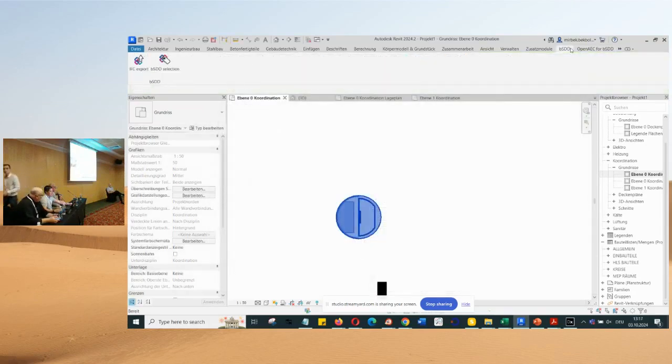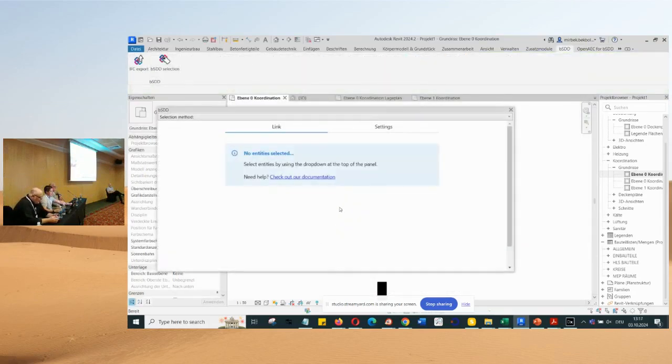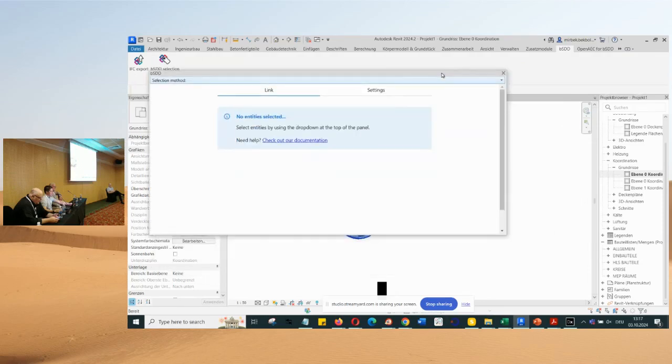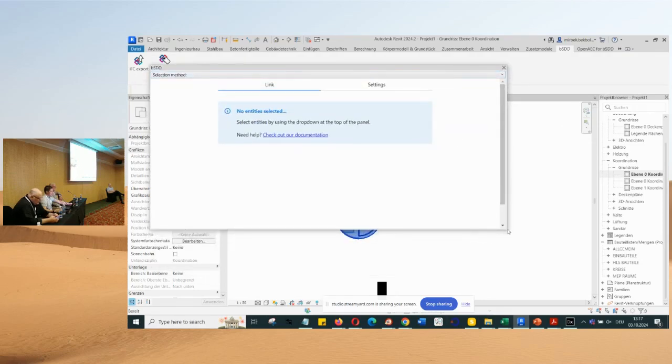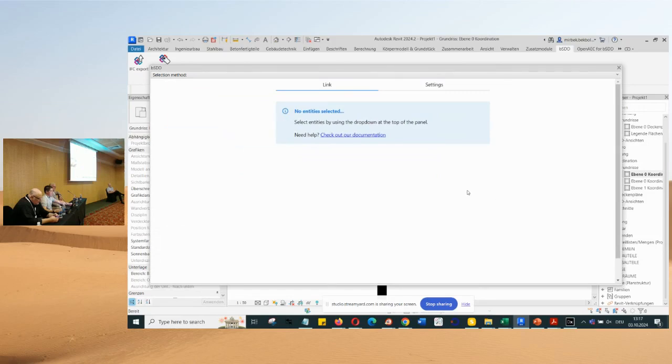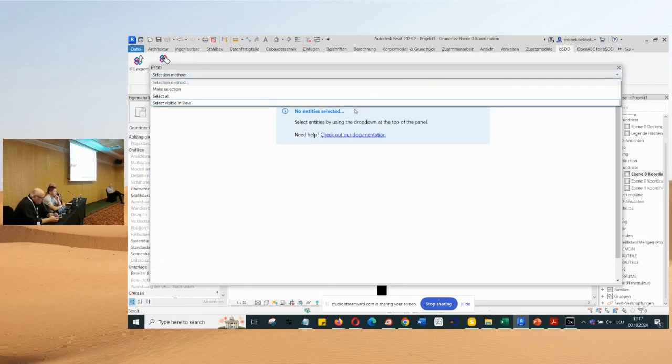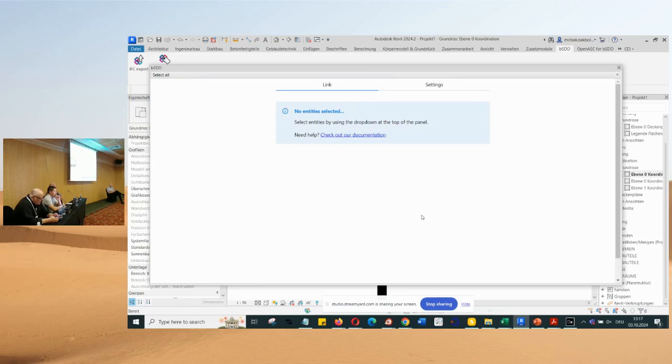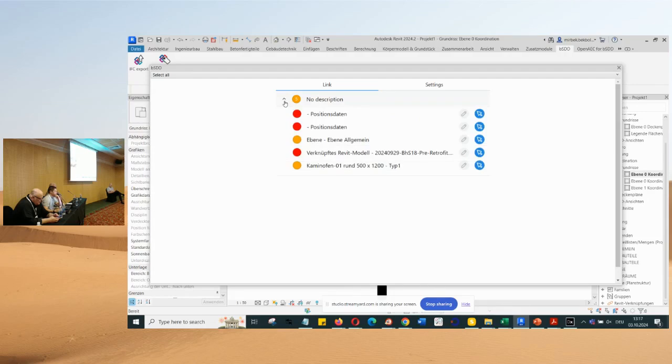We have quite a big factory that scans existing buildings the whole day and prefabricates new elements for them. We find that you don't transfer that much data, for example, from a point cloud to a new as-built model, because the existing building is curved. Every time you make a new model, you get a loss of data or less accuracy. So we are more into cutting out the point cloud for the part we need and getting data from it, but not modeling it again. My suggestion: watch out when remodeling something, because it's always less accurate than the real starting point.